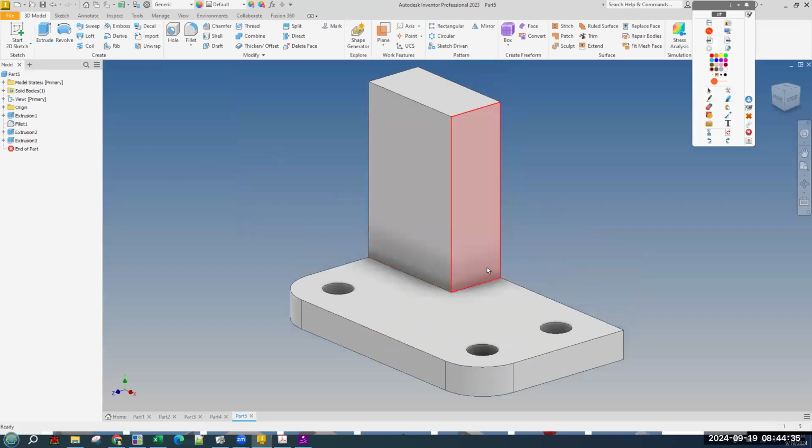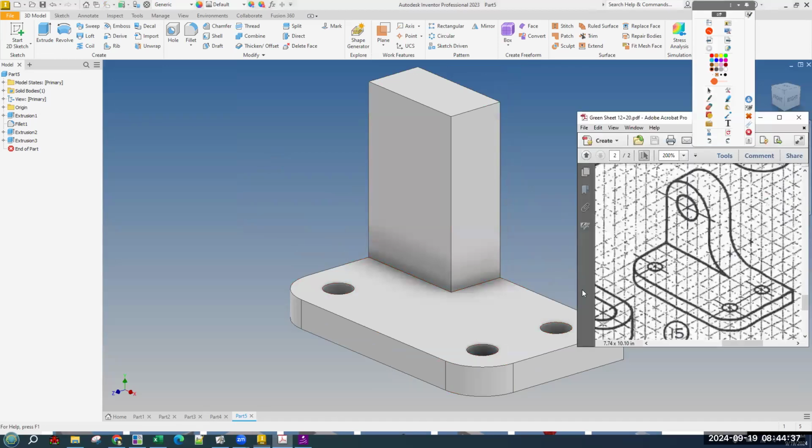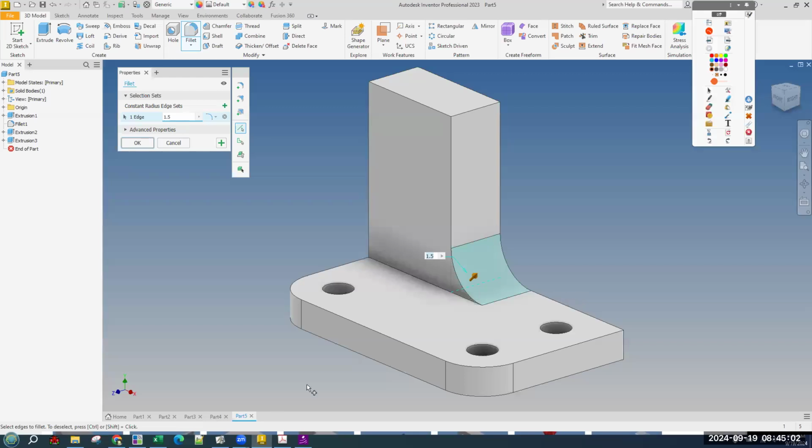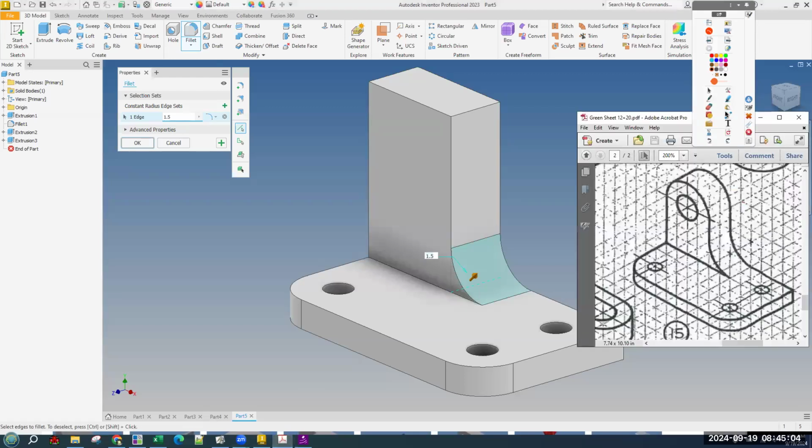Okay, and the way we're going to make this, I said it a second ago. The way we're going to make this edge right here, or rather this sloped ramp, is we're just going to get the fillet tool, but we're going to fillet this inside angle, this interior angle, and it's going to create material. It's going to fill in. It's going to fillet this edge, which let's figure out what the dimension is.